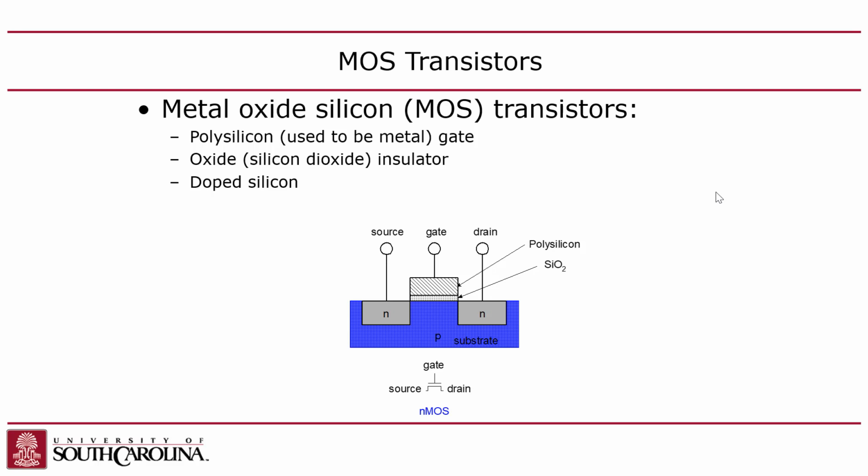But you can reverse the doping in parts of the substrate. These are called diffusion areas. These are little islands embedded in the substrate. They're little islands that you punch into the substrate. They don't go all the way through. They don't penetrate all the way to the bottom. They penetrate partly into the substrate, and you blast it with N-type dopants. That reverses the doping from P to N, but only for these little diffusion areas.